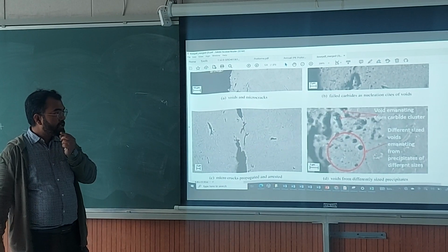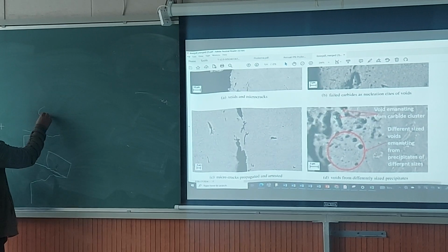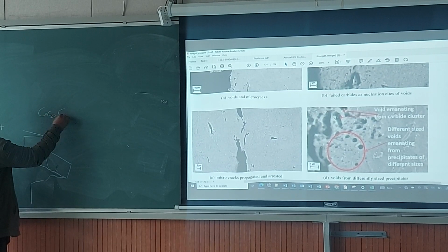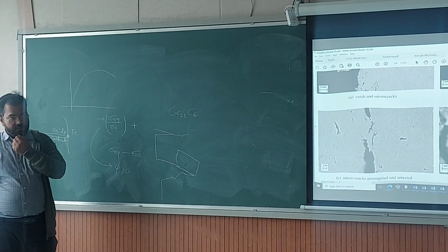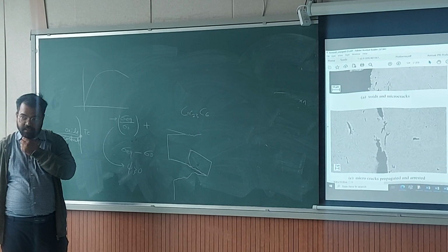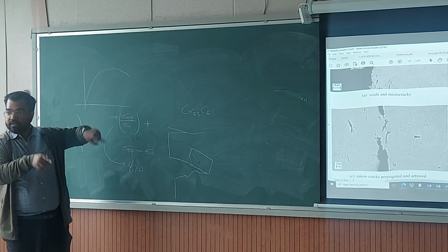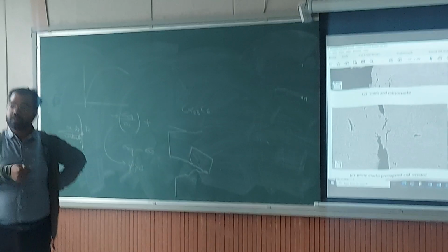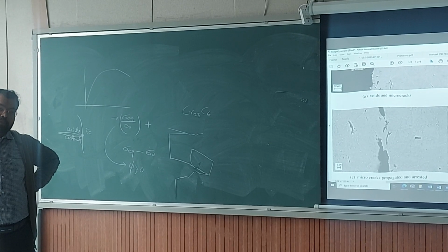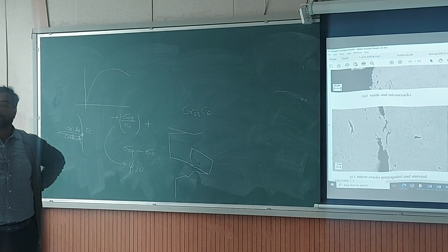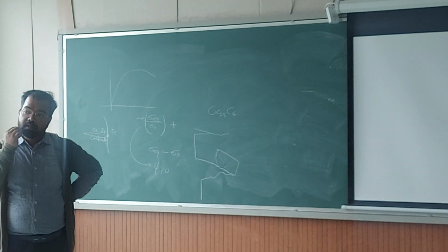Okay, so those are M23C6 carbides. Okay, those are Cr23C6 carbides. Okay, and this microstructure is of a tempered martensite structure, and the pattern which you see is the grain boundary of pre-austenite. So it was previously austenite, then it was quenched, it became martensite, and then you temper it. So although the martensite will lose its tetragonality, carbon will go out, but it will not look like ferrite. The microstructure will look like tempered martensite only.